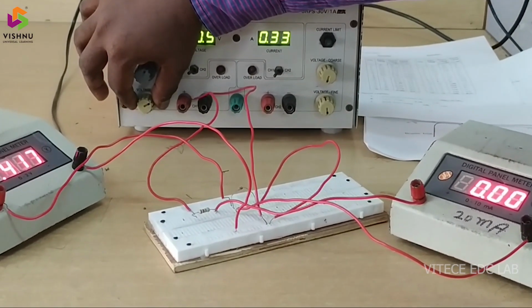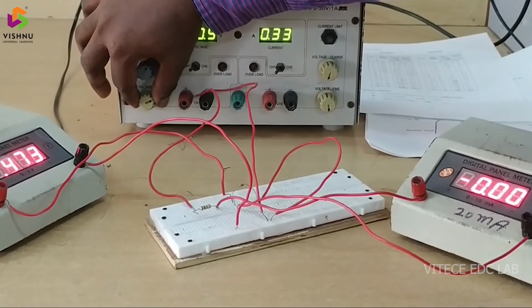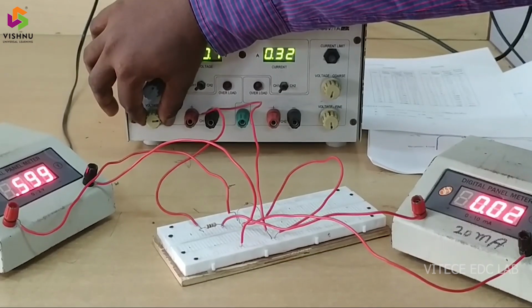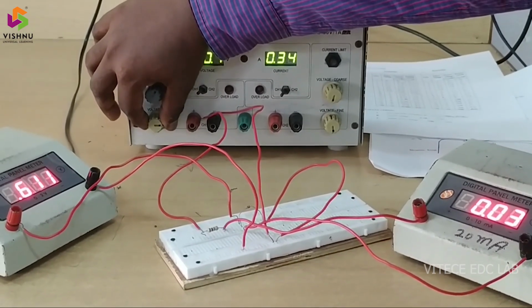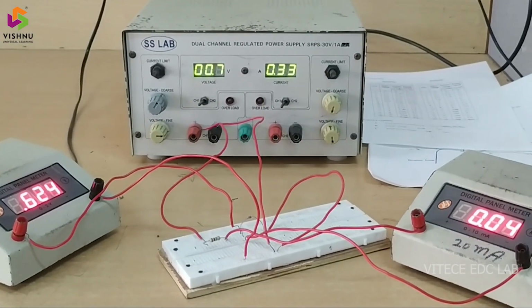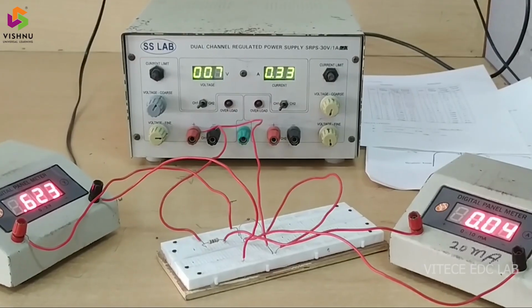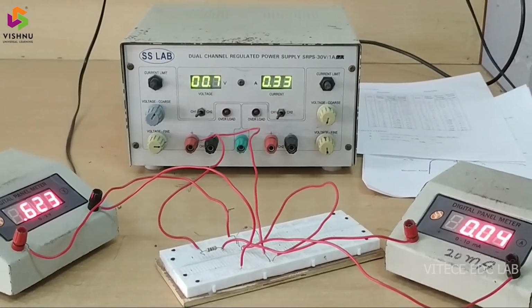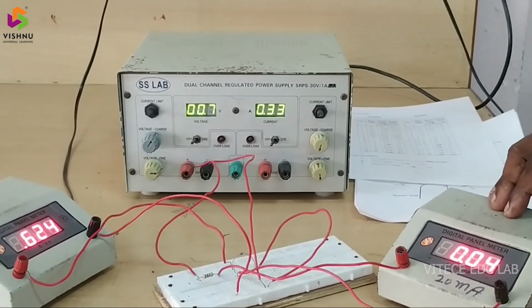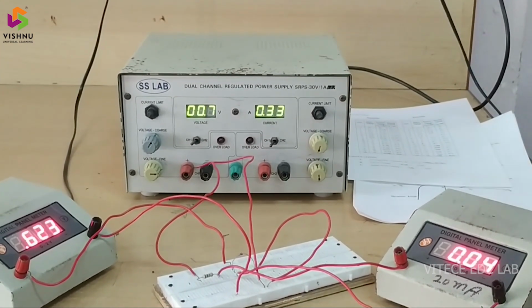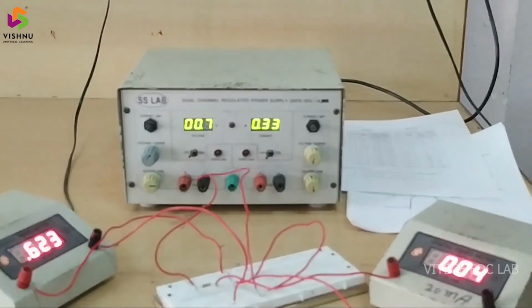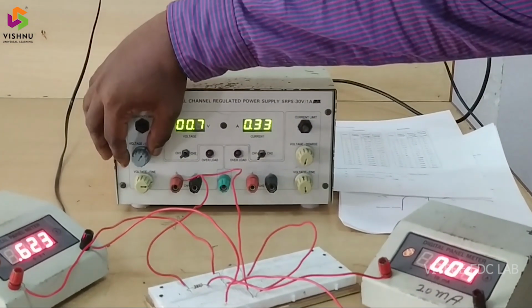The cut-in voltage of this Zener diode is slightly higher than that of the normal diode. It's almost 0.6. Up to 0.6 there is no current flowing through the diode. That's why the cut-in voltage is equal to 0.6 volts. As the applied voltage further increases, the current flowing through the diode increases. Similar to the diode, a small change in voltage can create a large change in the current, and hence the forward resistance is very small.